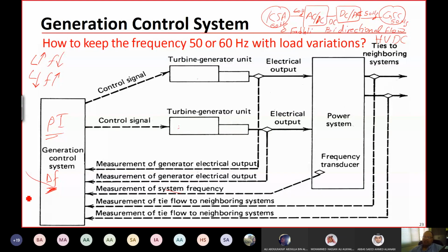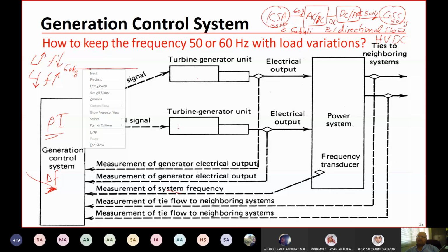This is done automatically, as you know, since the switching of the loads is continuous. If you go to the control center of one of the utilities, you will not get a constant 60 hertz. The frequency will be like a deviation around the nominal value.